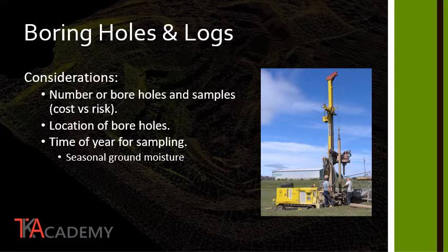Drilling boring holes and taking soil samples can be equipment heavy and labor intensive. Therefore, there should be a number of considerations to weigh before mobilizing a boring team on a project site. The first one being the number of boreholes and soil samples that are required for the project. The cost of creating a borehole and conducting testing should be weighed against the potential risk of not understanding what is occurring in the subsurface.